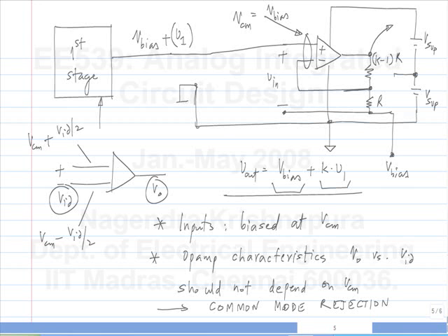Any questions on any of this? Now, you can also use this if you are in a lab and you want to design some circuit with a single supply, then you can use op-amps perfectly well. You just have to provide the appropriate bias voltages to the input and it will work. You look up the data sheet to see what the permissible range of input common mode voltage is. As long as you bias it within that, it should work.